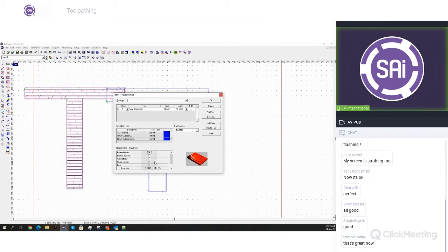Going back into our options, we'll just uncheck the inlay again. In here, we'll also be able to add bridges. So there's several types of bridges. To get a preview of these, you could consult the manual. Parameters for the bridge consist of bridge length as well as bridge height. And you can set a number of bridges or set it by distance, or choose to add bridges manually.